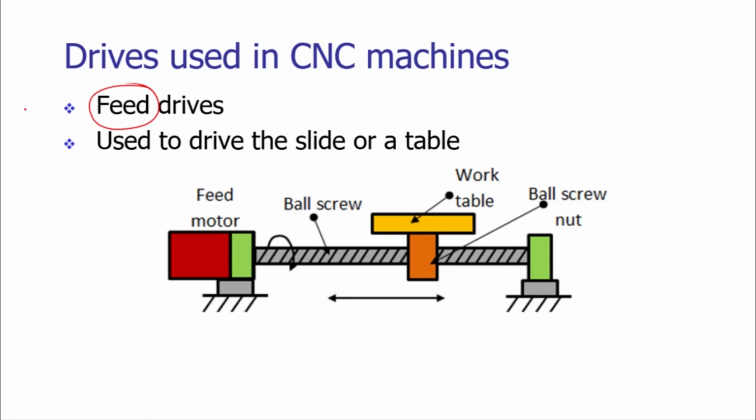The workpiece is rotating and providing the primary motion, the cutting velocity, but unless we move the tool with respect to the workpiece, we may not get the required size reduction. So for that purpose, we have to feed the workpiece to the tool.